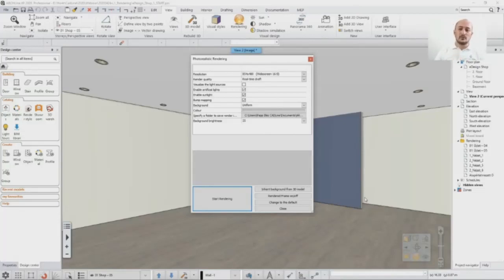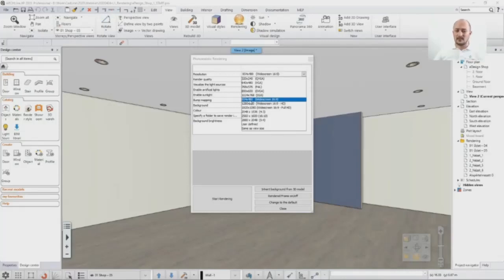So when you do the renders for yourself and not for your client, you should not go with high resolutions. Now, for example, talking about the widescreen resolutions that you can select here, this is a work, a study resolution. It's for yourself. When you do the rendering, you will see all the reflections, all the lights, even on the small version of the rendering, but it will render way faster than you would render, for example, a widescreen full HD, or even talking about 4K that is even longer.